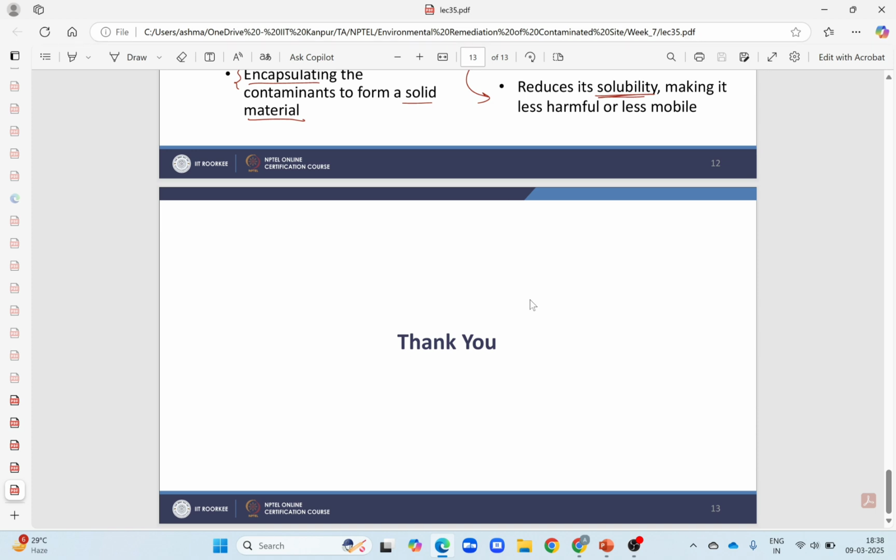C is determine groundwater flow and solute transport parameters along core of plume. D is compare the rate of transport to rate of attenuation using analytical models. E is locate source and potential point of exposure. And F is after all screening criteria are met, proceed with detailed feasibility analysis. So we have to select the correct sequence in which these steps are done.